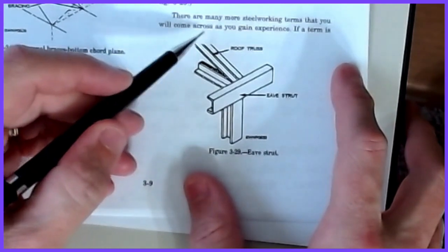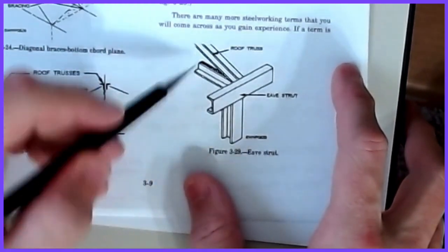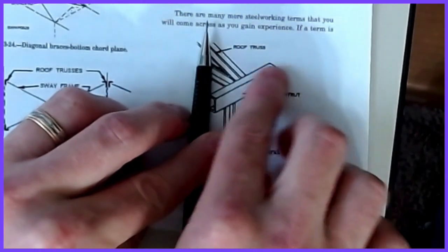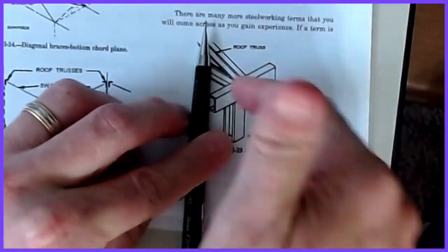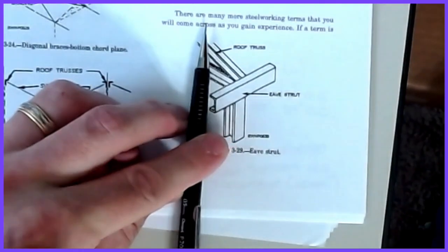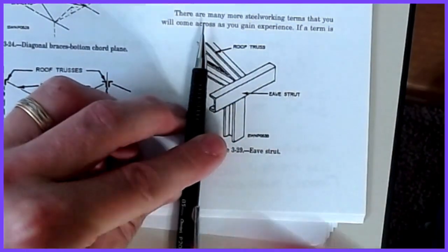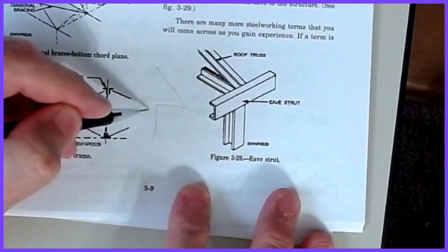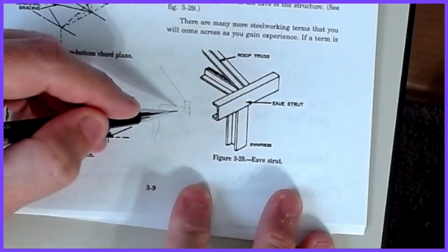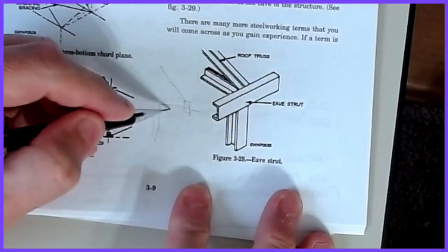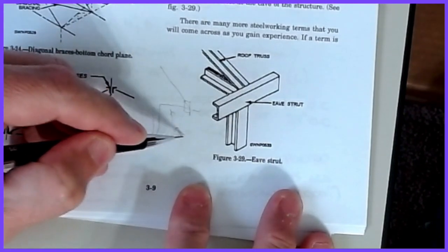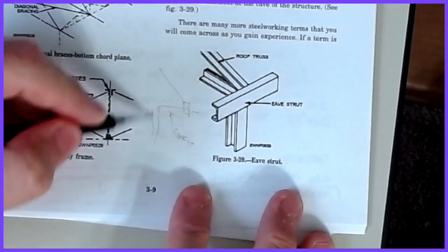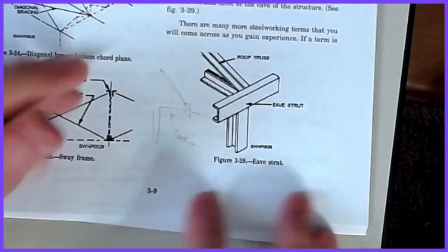And on your house, typically these are overhung from the outer wall, but the outer wall might be sitting about here, and then this is out, and that is a runner plate that runs between the trusses or between the roof members, and then a soffit would be that undersurface down underneath. If it comes down and does something kind of like that. Here's my eave. So that's this piece, and then this is my soffit. It's S-O-F-F-I-T. Okay. And so that's another term that you'll hear used a lot in structural engineering.